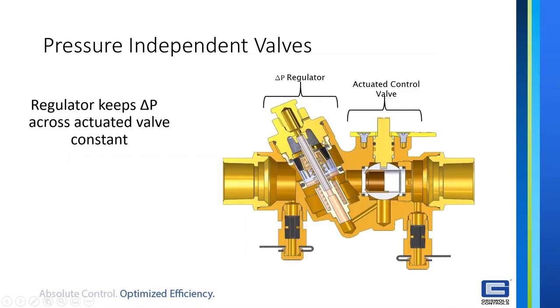Well, this pressure regulating diaphragm cartridge maintains a constant pressure drop across the optimizer, or across the actuated ball valve. Same principle in our other valves that don't use a ball, like a globe style in the MVP, where the pressure regulator is actually maintaining a constant pressure differential across the flow control device. So the control of the flow itself is actually coming in the PSID from the ball. So the ball is actually set at 4 GPM, 3 GPM, 2 GPM.